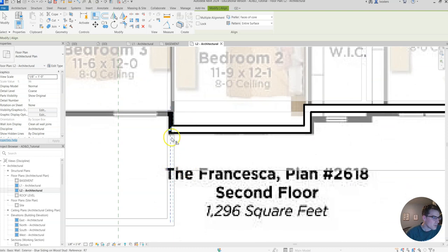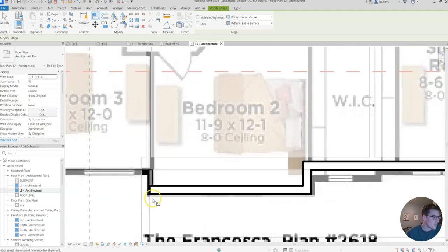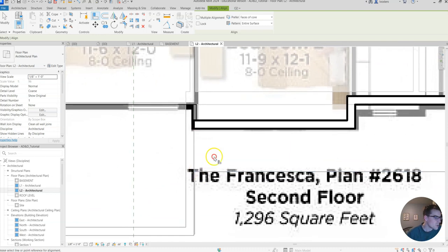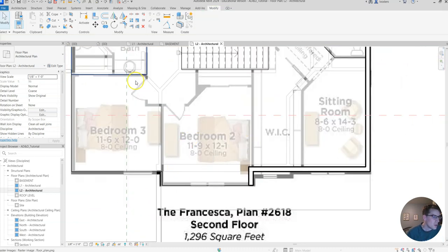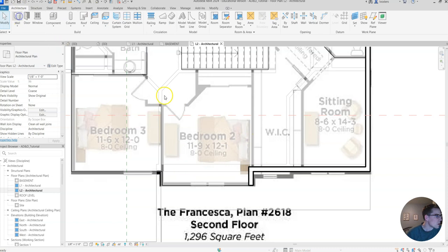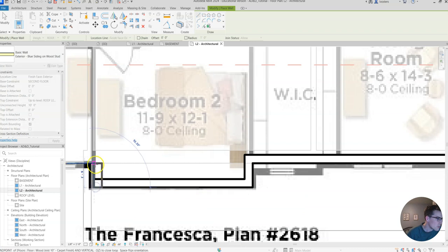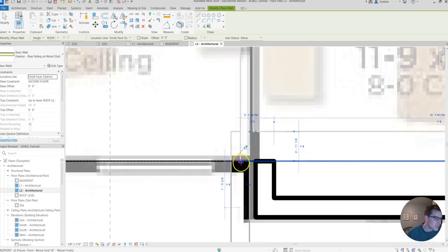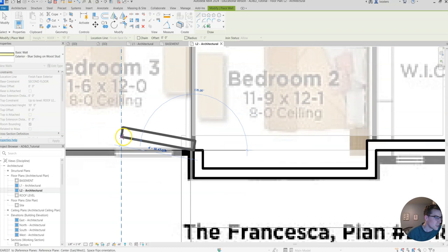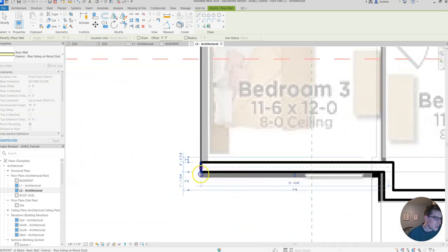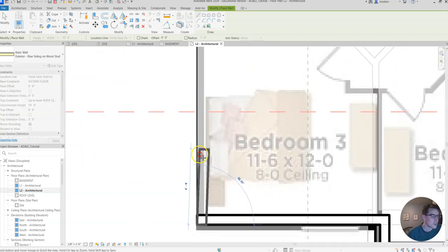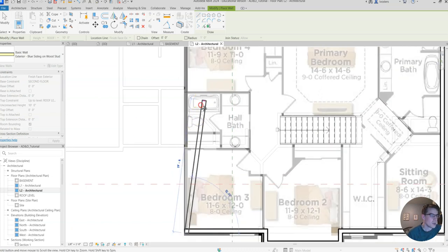I think all that did was just move this floor on this wall on the floor below, which I don't think we want. So let's try that one more time. Go to wall, blue siding. There we go. There we go. Sometimes the align tool is a little bit picky, so you need to take matters into your own hands and just kind of start fresh.